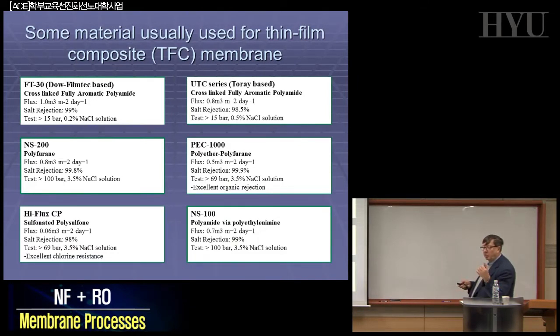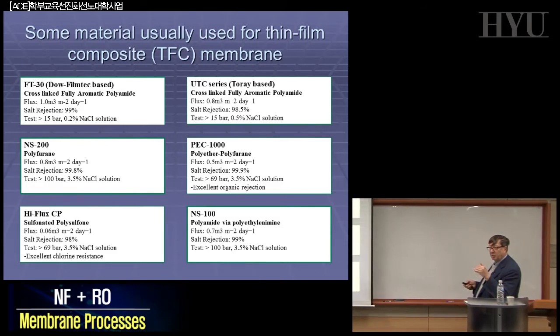rejection is no more, as we saw before, 40%, 20%, 30%. Here, there will be never a cutoff. Cutoff here does not mean anything. You will only talk about salt rejection, 99.9, 98.5, 99, 99, 99, etc. So very high value. Pressure, normally that you can obtain here, is of the order 20, 30, 40 atmosphere and more. Big value.